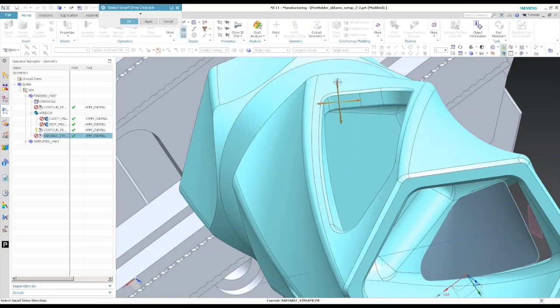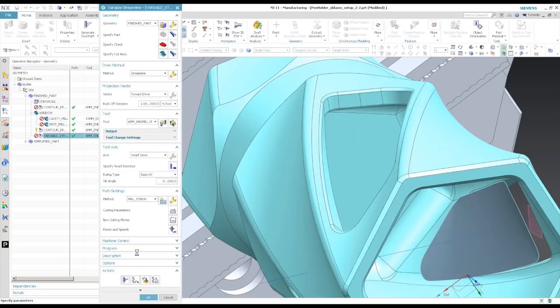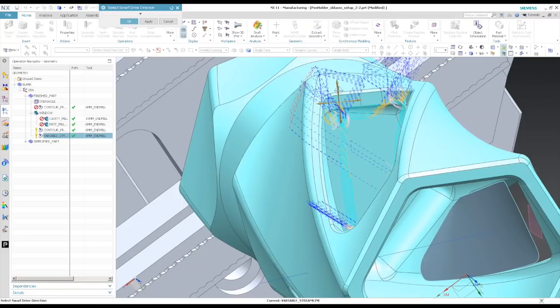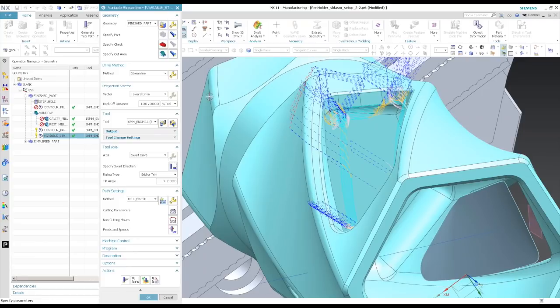So now you can see that the swarf, now that we have good UV lines, has better data. Because, well, this is actually base UV. The edge type of extraction doesn't always work, because sometimes you have edges that just won't drive the toolpath well. They just have too much tilt from one edge to another.